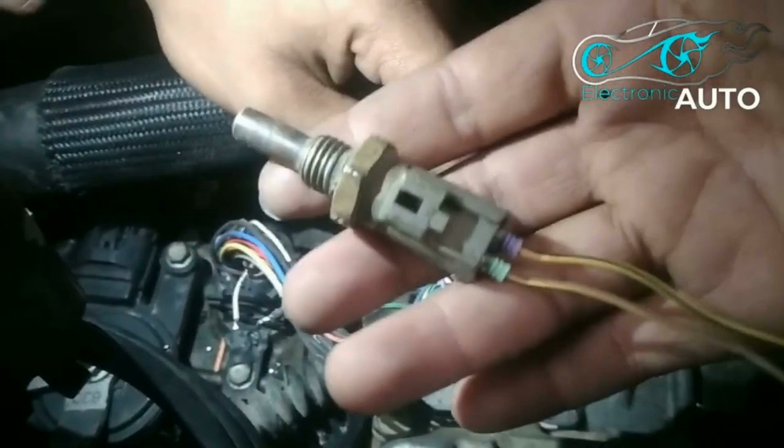Importance of automatic transmission: the transmission temperature sensor may be defective due to normal wear and tear, electronic faults, or exposure to extreme environmental conditions. A faulty sensor may transmit incorrect or inaccurate signals to the PCM, triggering code P0711. Replace the transmission temperature sensor.